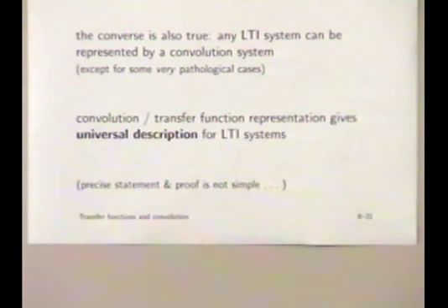So you have an airplane, and you say, we're going to do just one test in this helicopter. I have accelerometers, so I'm instrumenting the motion of the helicopter, and I'll say, I just want you to bump the thrust up for a second or two, and we'll record the altitude or whatever. Doesn't make any difference, right? Your pitch rate or your altitude doesn't make any difference. You just bump it up.